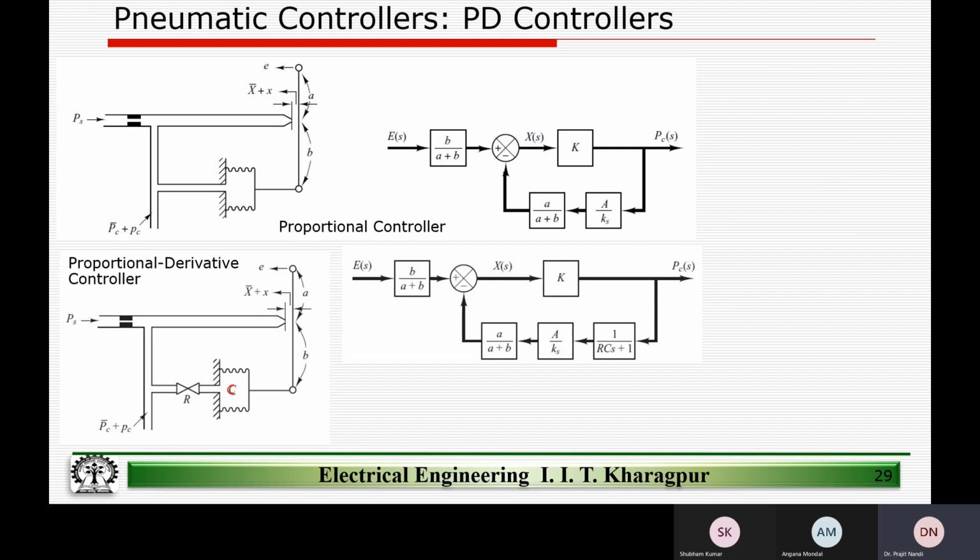also we are now treating it as a capacitor. See, this is like, think of it electrically, right? We connect a voltage source directly across a capacitor, which means the capacitor will have no meaning, right? I mean, that's the reason we never talk of a capacitor directly connected to a voltage source, right? Meaning this capacitor becomes redundant, right? Because it doesn't matter. Whatever is the voltage will appear across these two terminals, right?